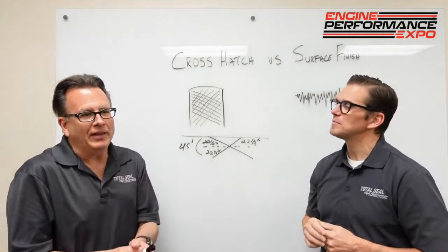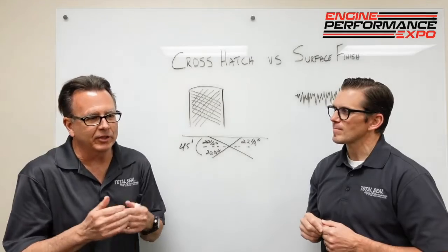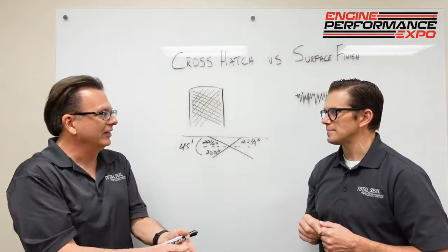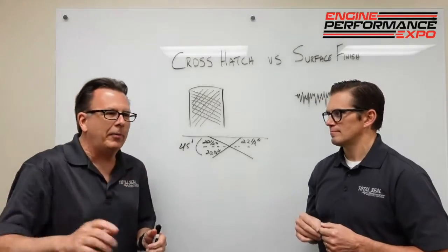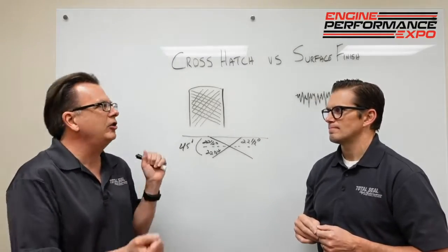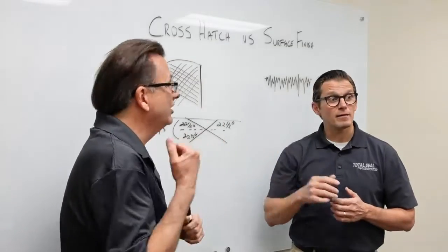Right. But with the older machines, you can get the correct angles, but you've got to be really careful. There's information out there that says set it on a B pulley and a D pulley and this pulley, that pulley. The thing you've always got to remember is how hard you load it is going to slow the speed on the head. Oh, that's true. Good point. So that's going to change the angle.